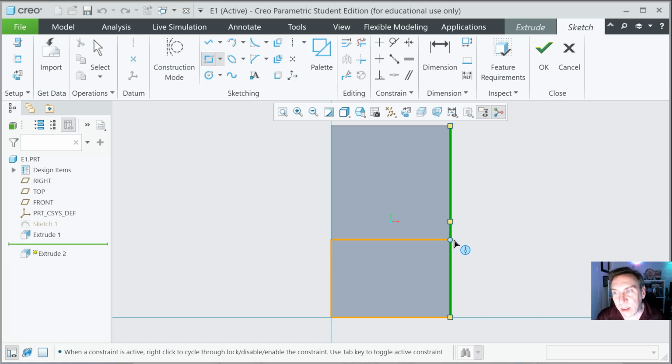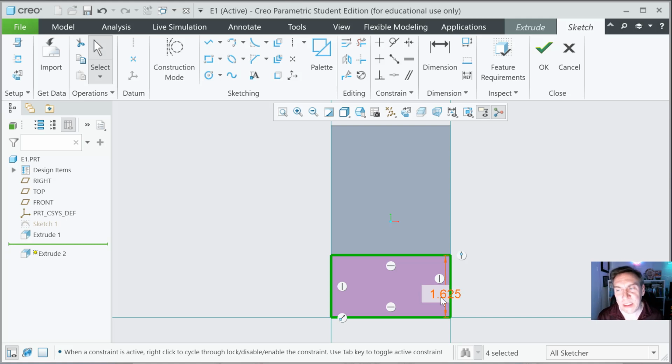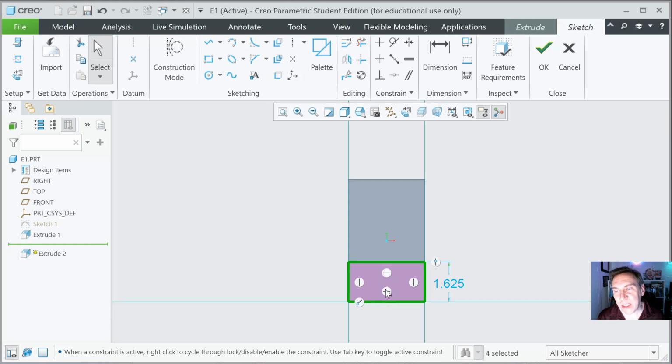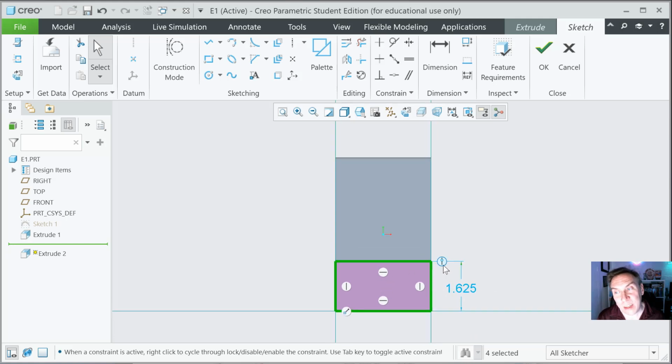But one other thing, what's this? That's the midpoint. We don't want it in this case, so stay below it. Click. And now, does anyone remember how to activate the dimensions? Okay, middle wheel click. And the dimension should appear. Now this time, notice we only got one dimension. Where is the bottom dimension? Well, that's gone. It's not needed because we created a constraint off of this referenced edge.